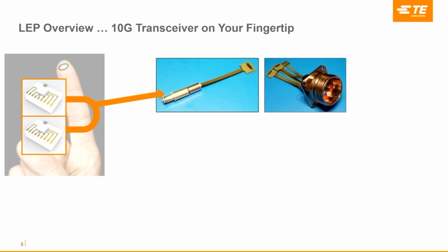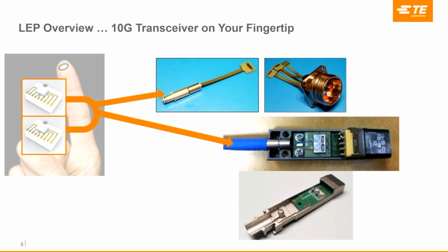I can take one of those engines and put that behind a fiber optic contact, build it into a receiver, and make myself a transceiver right on the panel of a box. So instead of running fiber into my box, I run electricity into my box. The conversion happens in the contact. Or if I have a system where I have a certified LRU, flight certified, that I can't take apart, but now I have them far enough apart that I need an optical link, how can I solve that problem? Well, I can put the transceiver or the conversion in the back shell of my cable assembly, turn that cable assembly into active optical. So think of a rugged version of a datacom AOC.